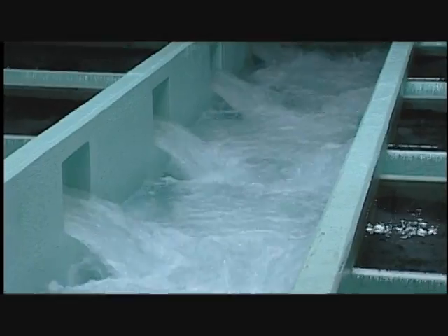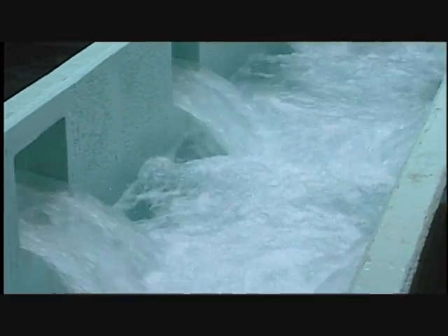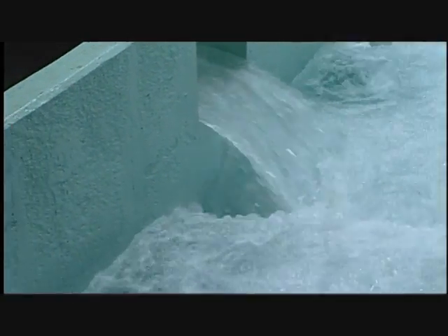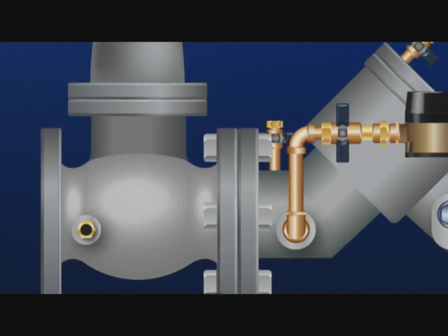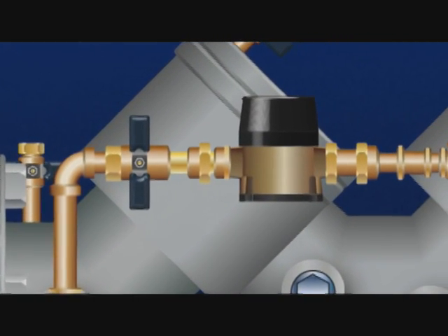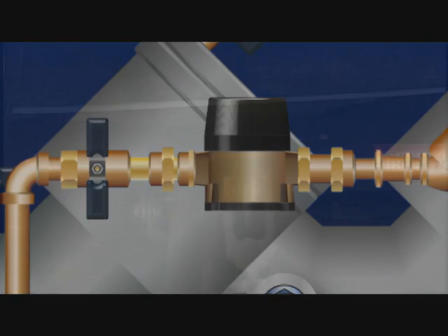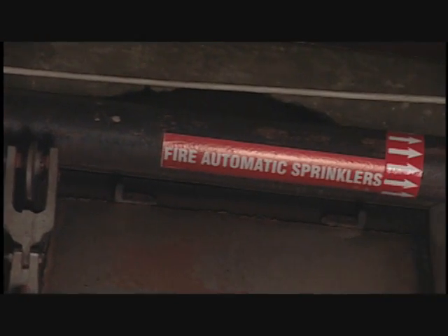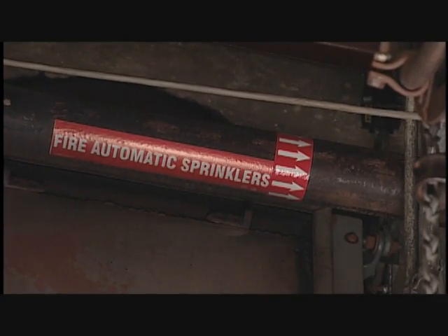Assemblies protecting the public water distribution system often have different needs than plumbing code fixture and appliance protection provides. It's more than placing a valve in the pipe. There are detection devices that monitor DCs and RPs that usually include a meter and bypass line for monitoring water loss, but more importantly, safety for fire protection.